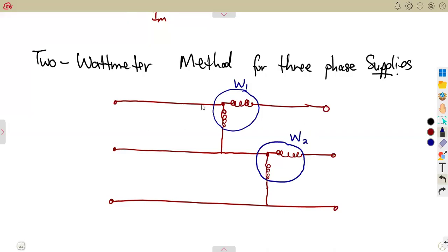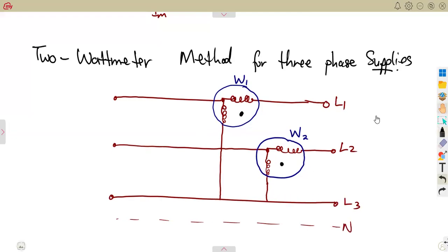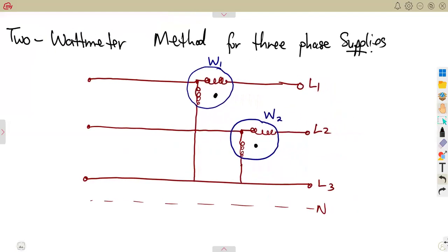All right, so there we've got wattmeter 1 and wattmeter 2. This must be to the ground here. So that is going to have live 1, 2, and 3, and that is going to have our neutral. Remember, this is a 3-phase. So with the wattmeter method, you can calculate the total power. There is a power calculated here, and there is a power also calculated on each wattmeter that you are given.